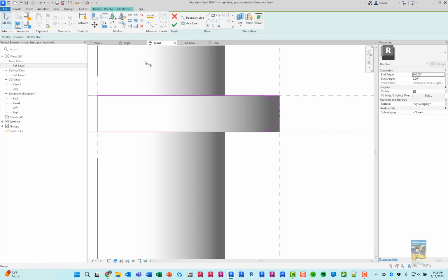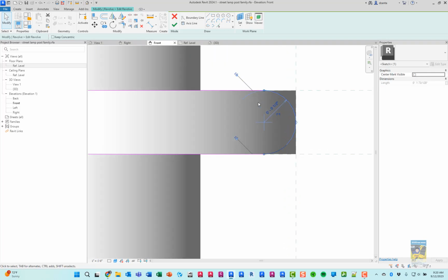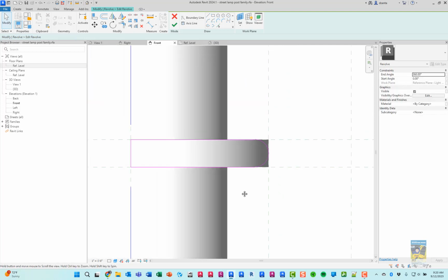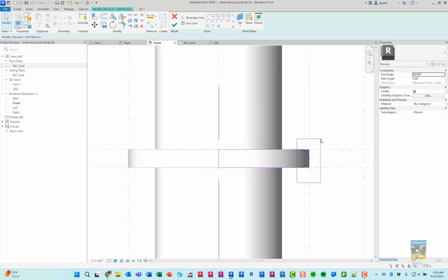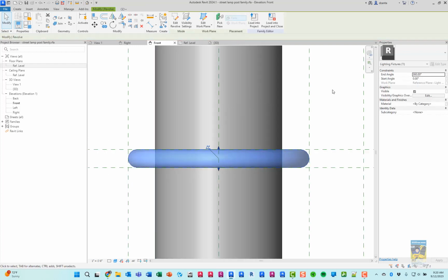And then we will trim the corner. TR is a keyboard shortcut, like that. And if we select it, you're going to see some lock and unlock functions for tangency between the line and the arc. Typically, you want to lock them in place so that they stay connected. And then because we already did that there, I'll just mirror this to this side. And then I'll delete this. Actually, I don't even need that. I'll just get rid of this. And if we finish it, there we go.